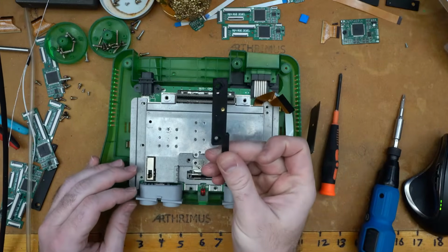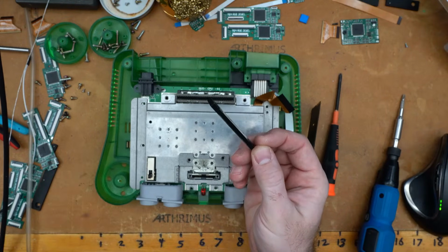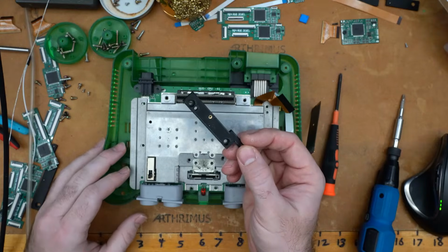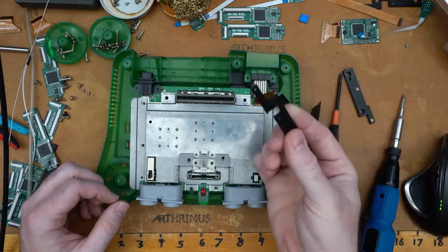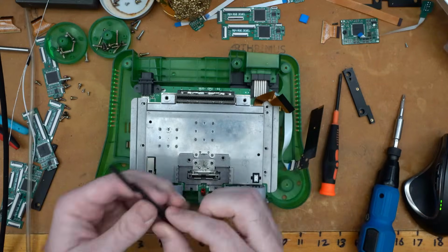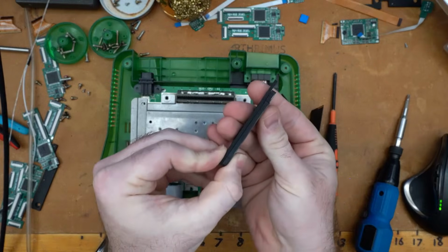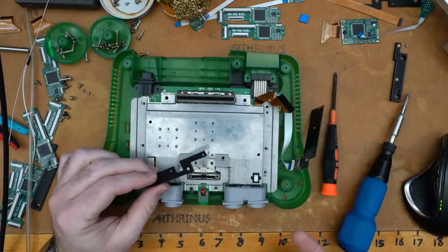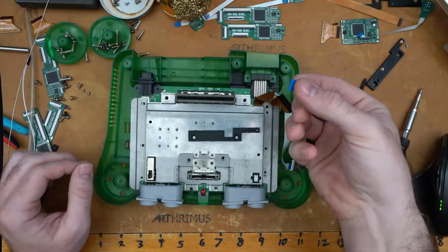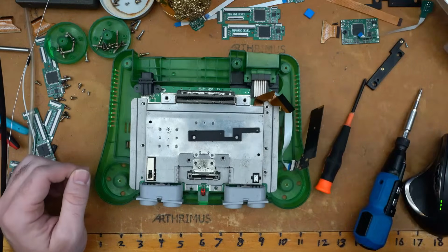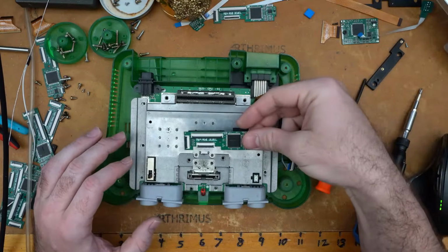Okay, now the 3D printed mount that comes with the Retro GEM is too thick for the Retro GEM and the Jewel to fit underneath the heatsink. So the Jewel kit is going to come with a thin 3D print. You can see the thickness is way less. So there's a thin 3D print that will fit both boards. Also, the thermal pad that goes to the heatsink will no longer reach the heatsink on this design, because the Jewel will be sitting on top of the Retro GEM.